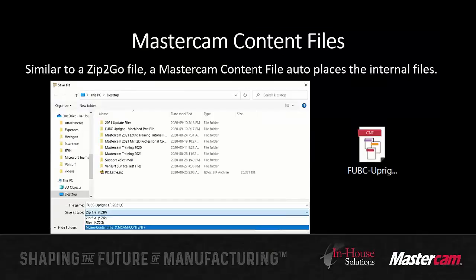So much like a Zip2Go file, the Mastercam content file is a one-click option for placing all of your post and machine definition files in the correct place while opening the part. This is great for transferring posts around the shop if you guys aren't using a server location for that. So basically by dragging this new file type onto your desktop and clicking on it, it's going to auto-place everything into your Mastercam setup files, so you don't have to worry about undoing the Zip2Go and moving everything into the correct folder. It removes the need to do that for you.